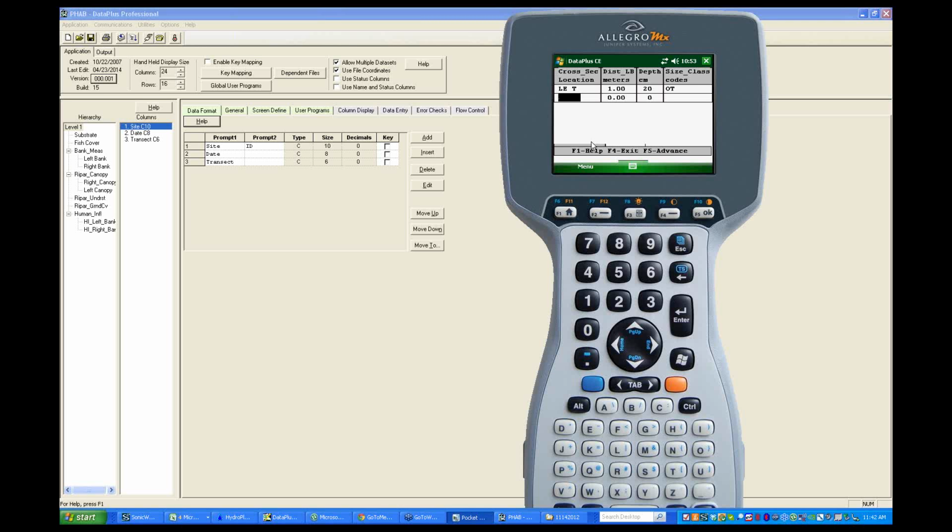And as Trevor showed, a really great trick here would have actually been to set that up as an auto copy feature, so it would have just copied that left bank down there. If I move over to the 2 meter mark, just do the same thing. Take a depth measurement, reach my hand down in there, what am I grabbing at this point, and how embedded is that particular rock, piece of gravel, etc. that I put in there. And then once I'm done with this, Alt F5 takes me to yet another measurement that I would do for this, and on I would go.